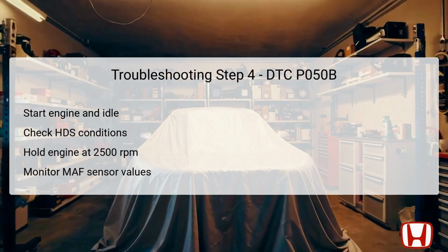In Step 4, the focus shifts to inspecting the functionality of the mass airflow (MAF) sensor. Start the engine and allow it to reach the proper idle state. At this point, confirm that the conditions for the testing are satisfactory. For instance, the HDS should show the engine coolant temperature (ECT) sensor at over 158 degrees Fahrenheit, 70 degrees Celsius,